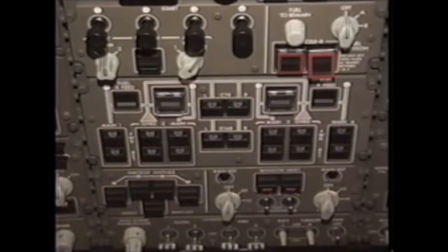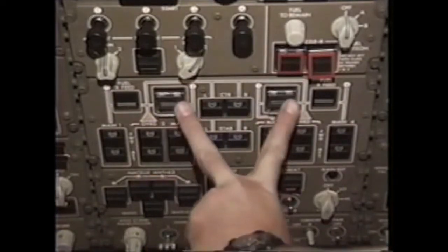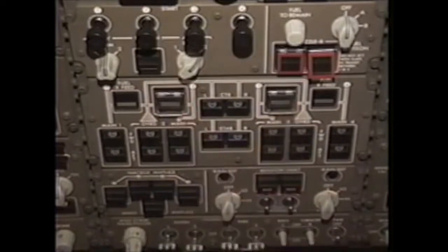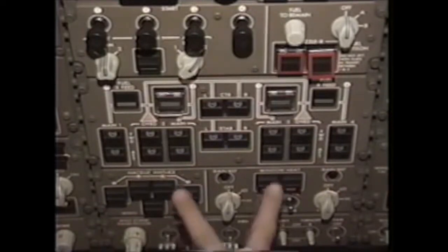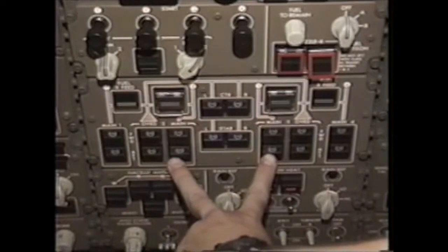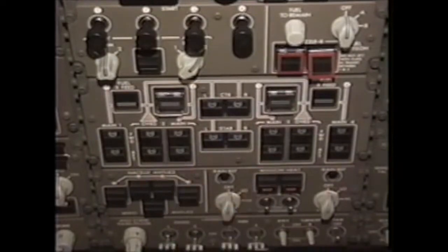The next fuel system change occurs automatically upon taxi out when the flaps are extended to a takeoff position. Whenever the aircraft is on the ground and the trailing edge flaps are set to position 10 or 20, crossfeed valves 2 and 3 will automatically close. As a result, the center wing override jettison pumps will continue to feed engines 1 and 4. However, the main tank boost pumps in tanks 2 and 3 will then feed their respective engine.